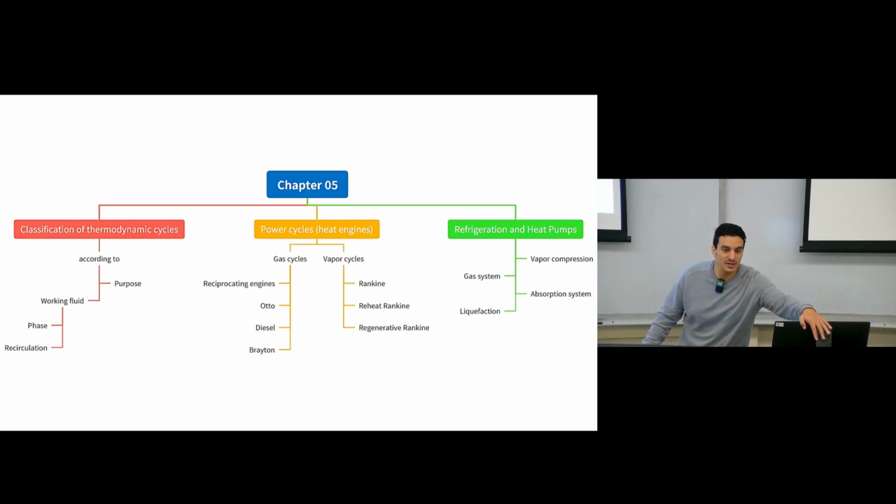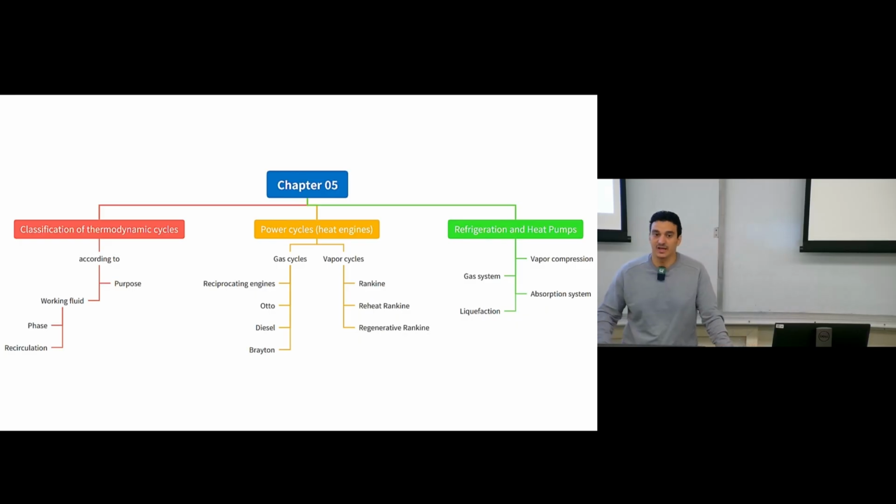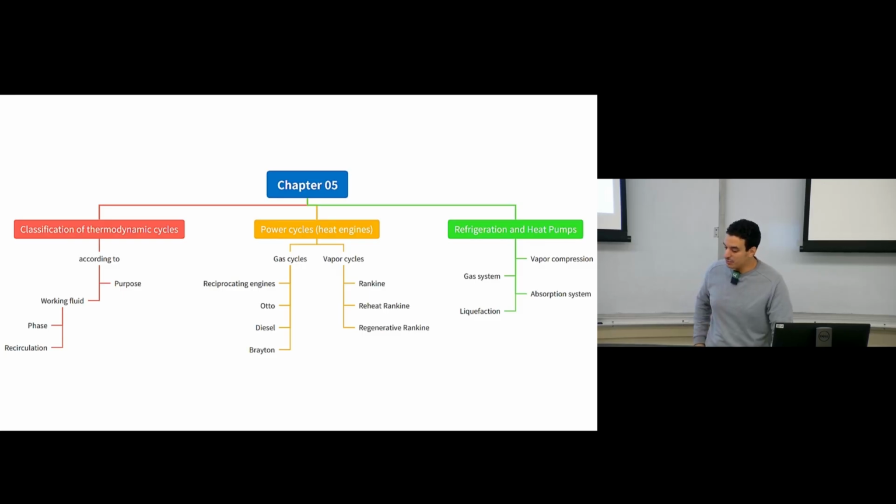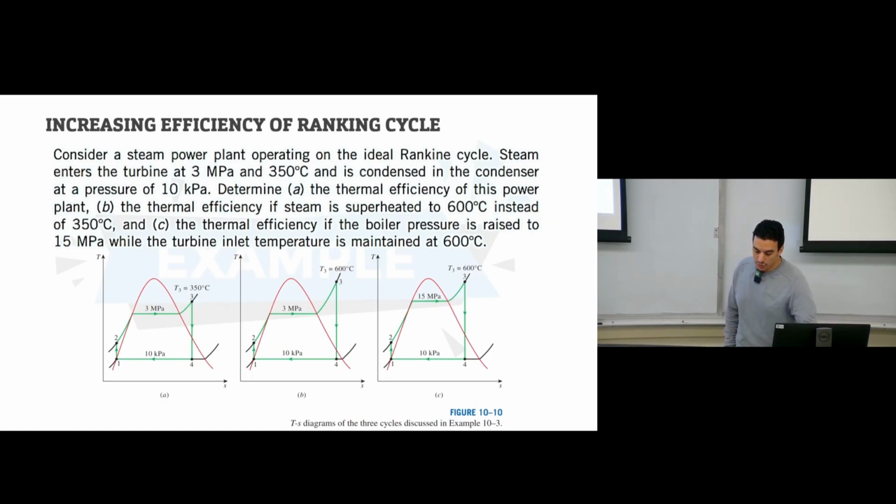Rankine cycle, this is the ideal real cycle that we have. And again, it has the same components, it has 4 steps, 2 isentropic, 2 isobaric, not isothermal. Instead of isothermal, as we are using in Carnot, we have isobaric steps, as we are doing in Rankine. And we showed how we can calculate the thermal efficiency of the Rankine cycle. And last lecture we had an example to solve and to find the thermal efficiency of the Rankine cycle. Today we will have another example. This one is completing what we said in the previous one.